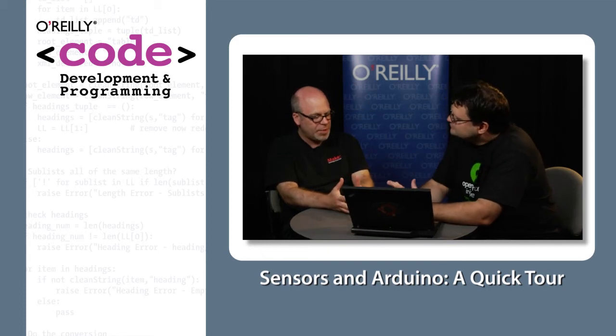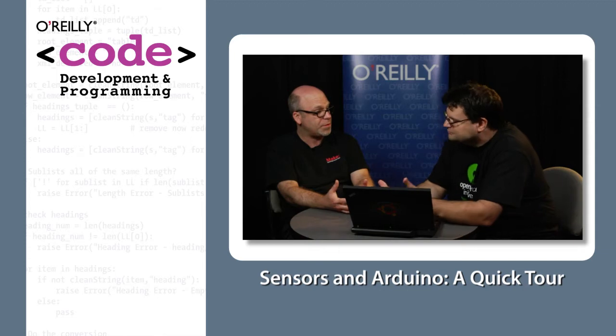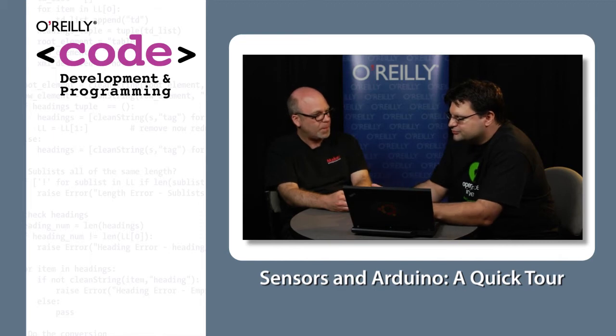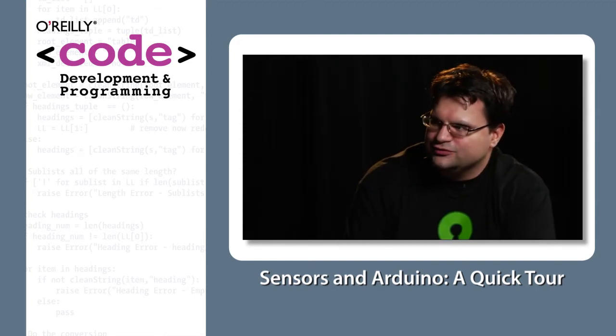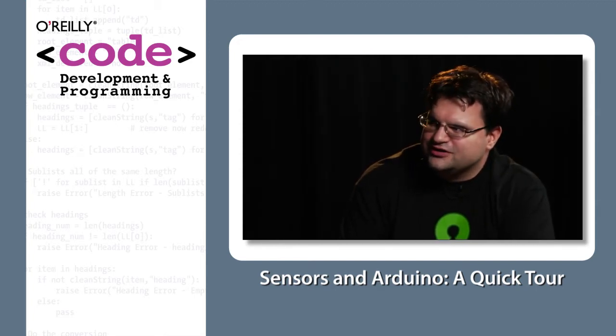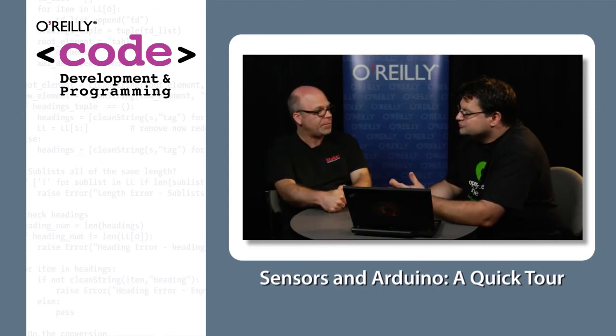And that's a piezo. A lot of people think of piezos as things that might make a buzz. They use them as buzzers. That's also true, but they're also sensors. You can use them as sensors because when you put power into a piezo, it generates movement. But conversely, if you are putting force into it, it generates current. So you can use it as a knock sensor. That too. Right? That too.